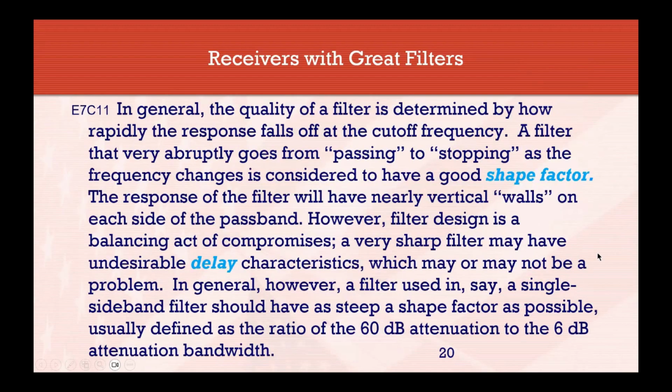Response of the filter will have nearly vertical walls on either side of the pass band, or the skirts, as they may be called. The filter design is a balancing act, of course. A very sharp filter can have some undesirable delays in it, especially in the digital world. The delays are used for other things, and that can cause a problem if the signal is delayed. It may or may not be a problem depending on what follows it.